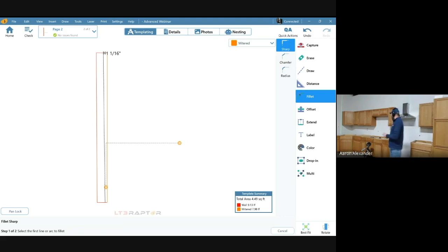So what I'm going to do is actually set my laser. I'm going to fold my legs in right here. I'm going to drop one down to about the height I think I want it at, even though they're not spread out, about that high. And then I'm just going to drop my other ones to match it. Then I'm going to spread them. And really the idea here is that the hole right here is where my laser light is coming out. I really just want this hole to be just higher than the countertop we have installed here, so I can just shoot to the back wall.